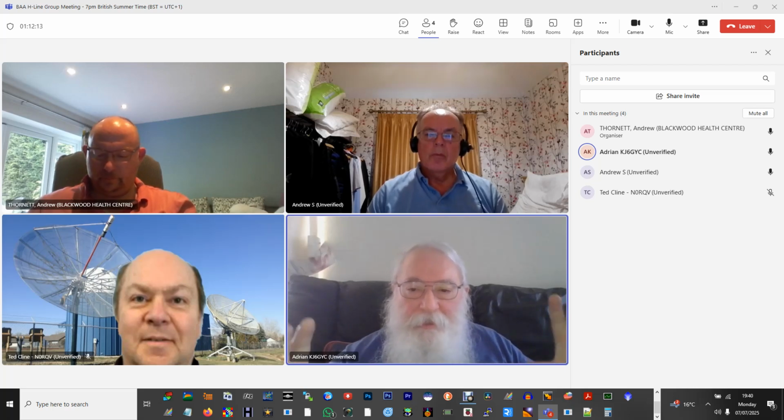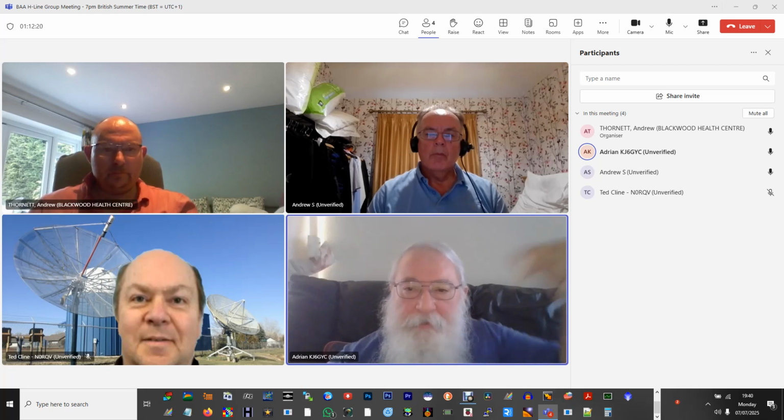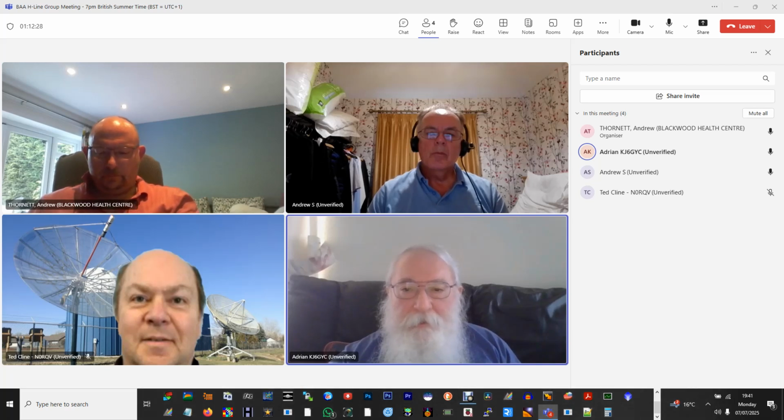On the antenna, I'm utilizing two linear probes, orthogonally at 90-degree angles, to obtain those two polarizations, and then using the Duo to essentially do a 2-for-1. So you're doing the reception with the two polarizations, so that you can average them together and perhaps get a little bit better signal to noise ratio.